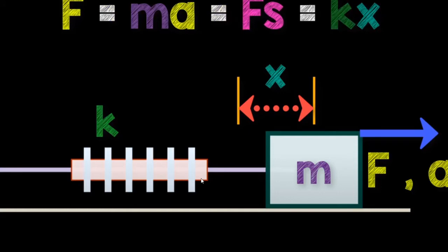But if you want to build a smaller one, you normally need to sense the distance. For sensing the distance, there are three kinds of sensors. One is called resistance. For example, if you have a potentiometer, you remember if you move a little bit of the potentiometer, one of the ports, you will change the resistance. So this can be an idea of how to measure the distance change based on the resistance change. This is called resistance sensing.